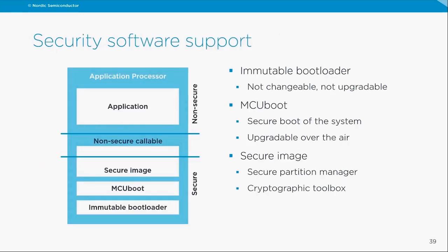We also have security software support. And this is several pieces. So at the bottom you have the immutable bootloader. This is not changeable or upgradable. So after you have flashed it, it cannot be changed. And it's the first thing that is executed at boot, and then it will